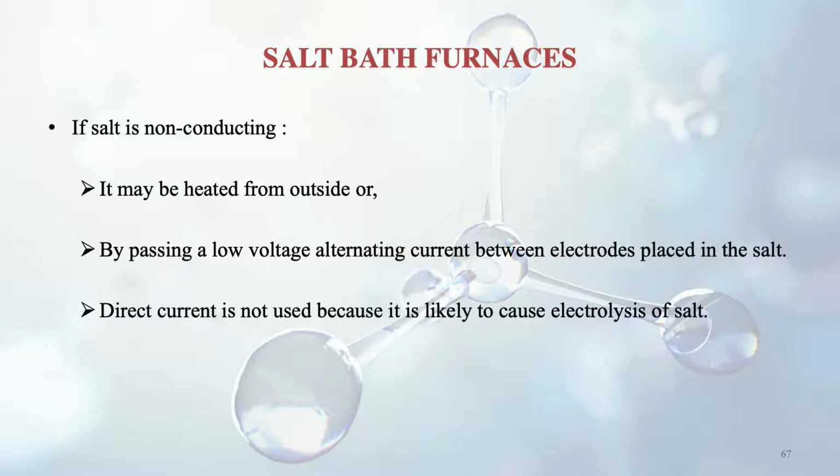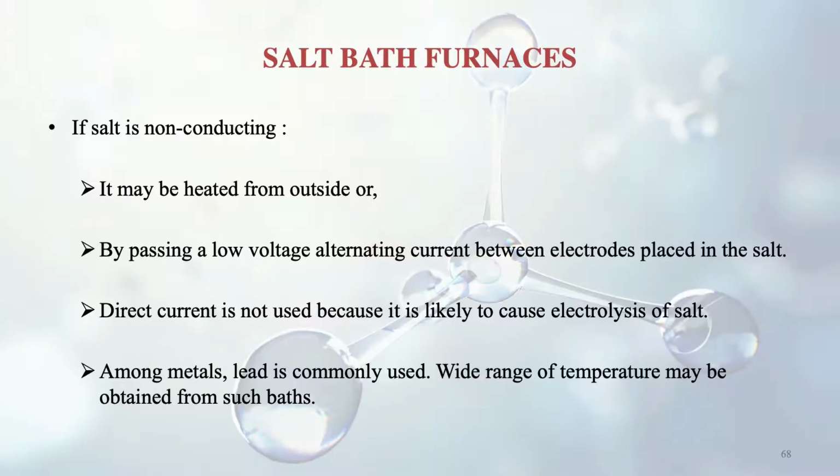And we don't use direct current in this case because it will result in the electrolysis of the salt, so we use alternating current only. And among metals, lead is commonly used. Lead salt bath is very much used. Wide range of temperature is obtained from such baths.